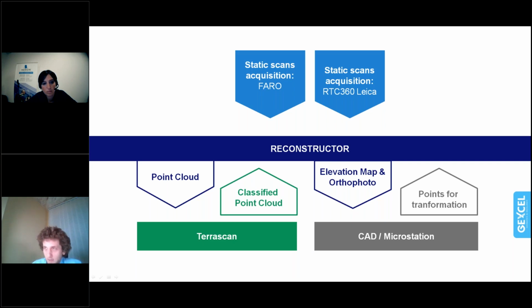In this exact department, we used the Faro scanner, but the rest has been done with the Leica. Again, not a problem. You can choose your instrument, whatever you have. The point cloud will get into Reconstructor one day or another. The point cloud has to be classified because you have the walls, the columns, maybe the scaffolding, the reference fields in the case of Faro, or any other instruments that might be present during the laser scanning, and you do not want them present within the point cloud.